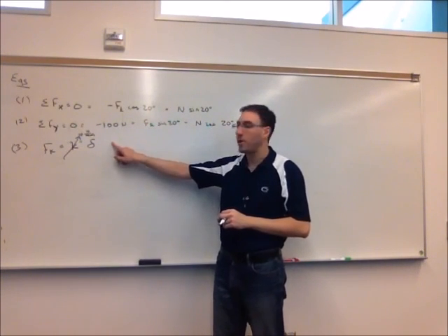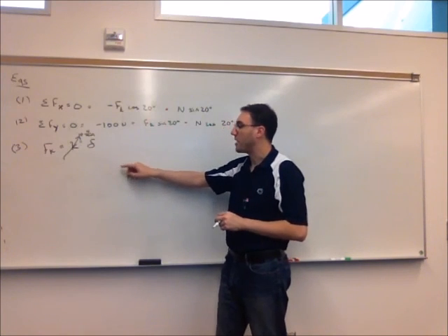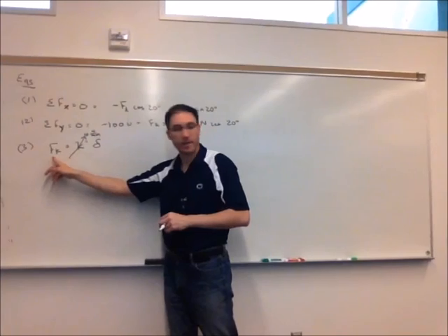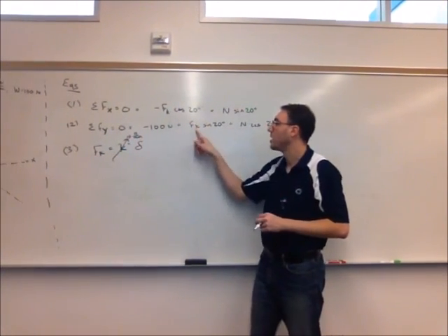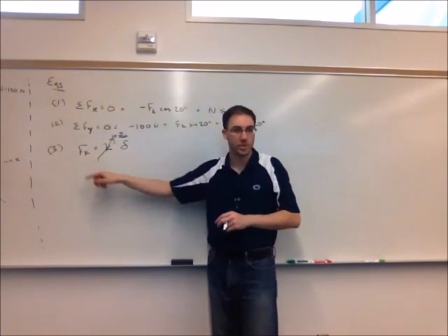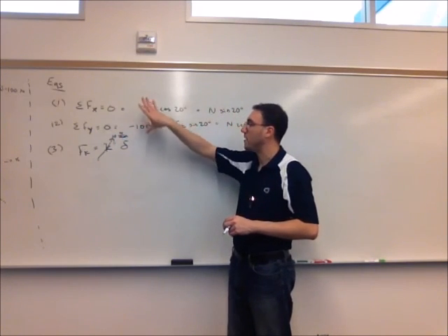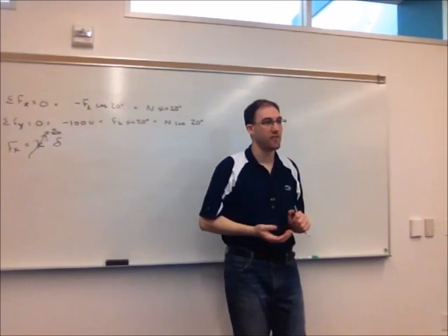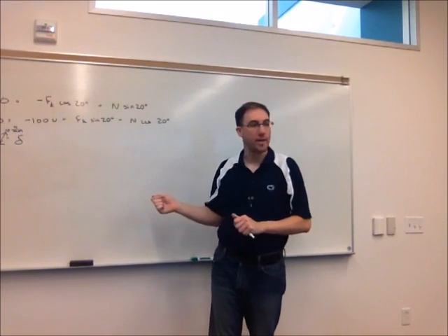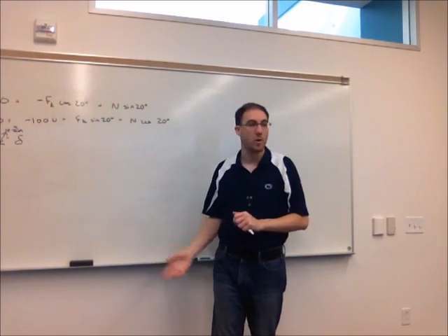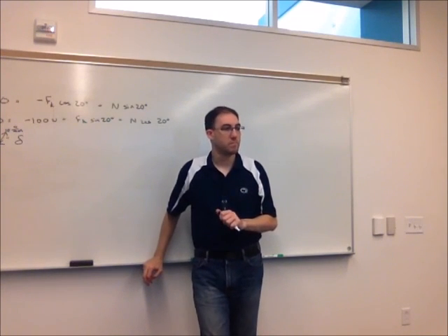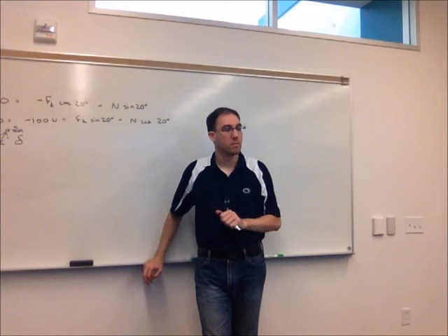So if we look at equation 3, this is just Hooke's law here. We've introduced one more unknown and one more equation. Fk is an unknown, but it's not a new unknown. It appeared in all of our previous equations also. So in this system, we have 3 equations and 3 unique unknowns. So we, again, have a solvable system, and we now have an equation with delta, which is what we ultimately were asked to find.